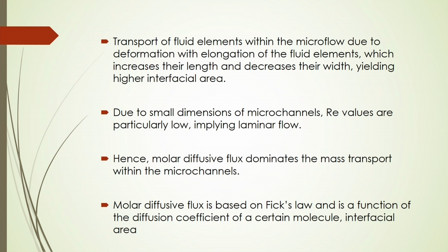Due to the small dimensions of the microchannels, the Reynolds number, which depends on the velocity of the fluid, the geometry, and the properties of the fluid, is particularly low, which implies laminar flow, and in that case molar diffusive flux dominates the mass transport within the microchannels.